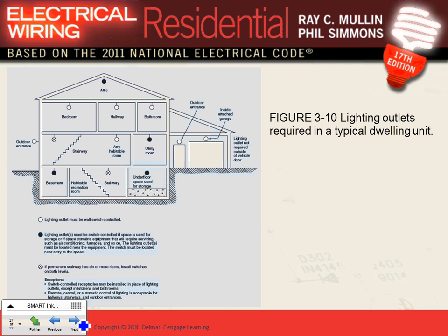But remember, when we do commercial, if you have rooftop units, a chiller, a cooling tower, or any of these mechanical units, you are required to put a 15 or 20 amp receptacle. Usually we dedicate a circuit to them for maintenance. This is just for maintenance, not to power them. You're working on them and you want to plug in an extension cord so you can work on them. To power them, it's 30 amps. We talked about the branch circuit, 30 amps to power them.